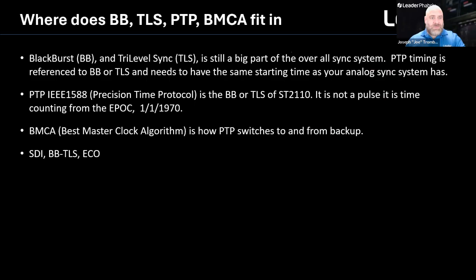So where do Blackburst and tri-level sync, PTP, and the BMCA all fit in? Blackburst and tri-level sync remain important on the SDI side, while PTP becomes the timing basis for ST 2110. PTP is not a pulse reference, it's a time-based system derived from epoch, and BMCA is the mechanism that determines takeover between the timing leaders.